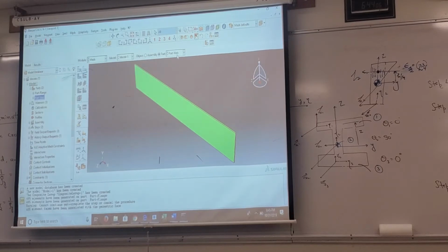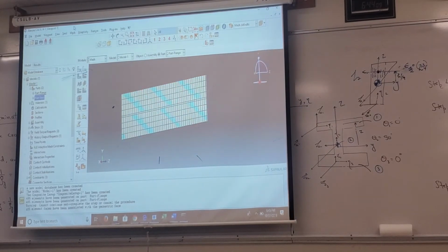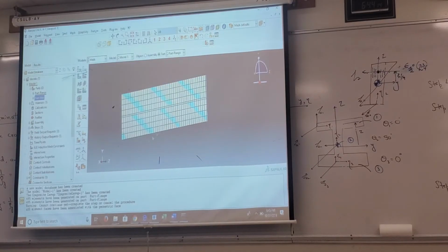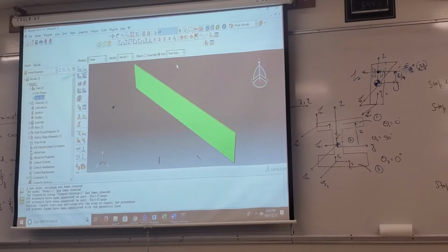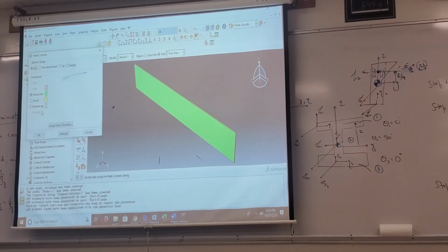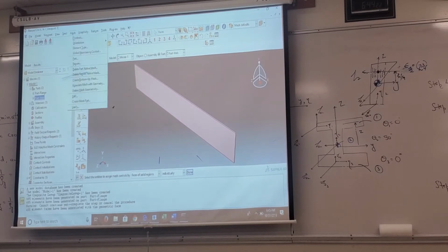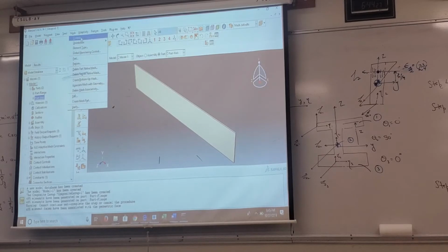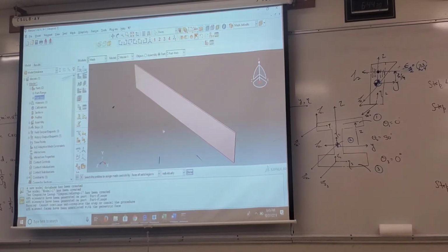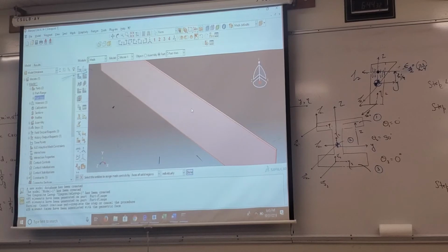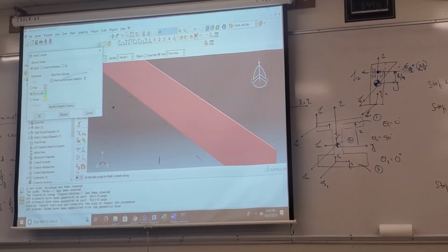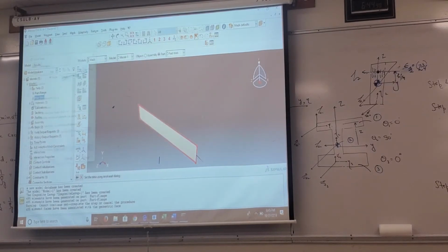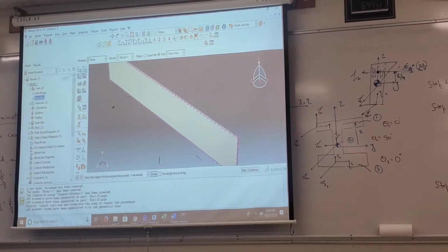Similarly, we have to go for part web, but before I go to part web, let me also do a quick change here. Element type has to be continuum shell. So that's done. Now I am ready to go for part web. Again, mesh controls bottom up. Mesh element type is continuum shell. Mesh again controls, now faces of solid regions. Pick any faces that you need. Put it as a structured mode. Apply seeds, the same size as I have been using there.